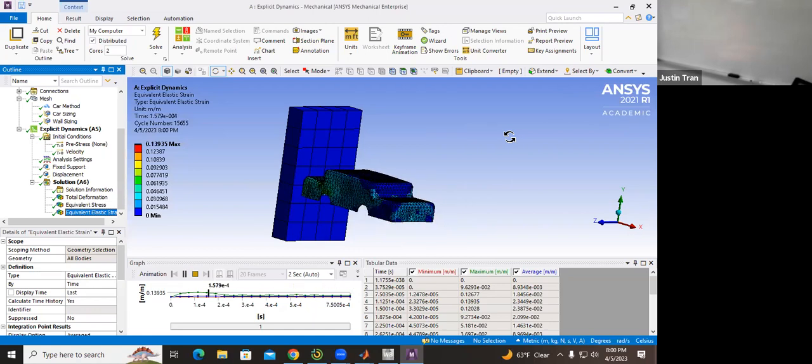There's going to be some discrepancies, I'm guessing you guys use the same one. There's going to be some discrepancies because you saw the car kind of jiggles. There's a little bit of randomness in how deformation is going to get distributed throughout the part. Part of that depends on the mesh. Because we're using linear models, they're comparable. Even if you use the same mesh settings, there's some randomness in how the actual elements behave.